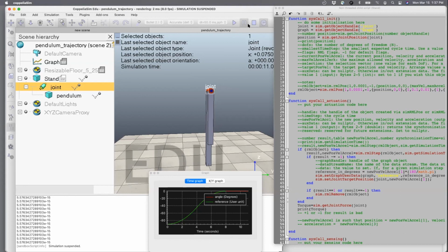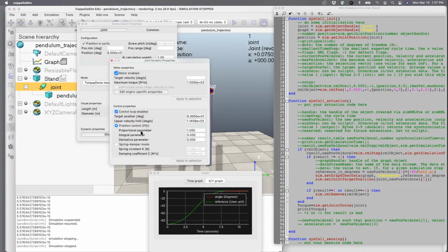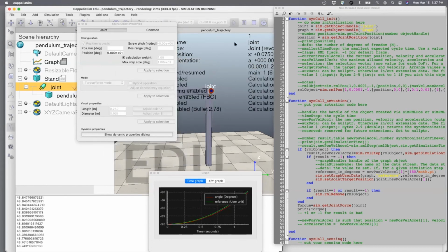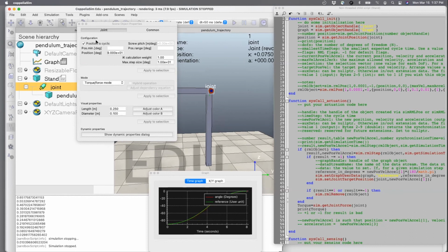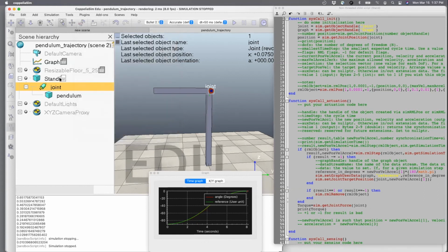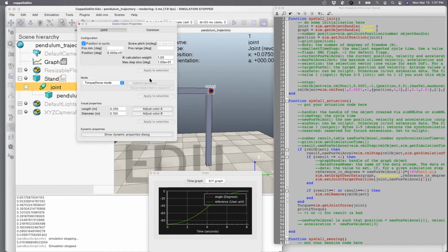The other thing we notice here is that these PID control gains are really something you need to work on. Let's try 0.1 and see what happens. There's a tracking error, as you can see. By the way, you could also have plotted the error, maybe that makes more sense. You can go here, and I won't do it, but instead of plotting the joint reference, you can plot the error and see how much it changes. So clearly 0.1 is too low.